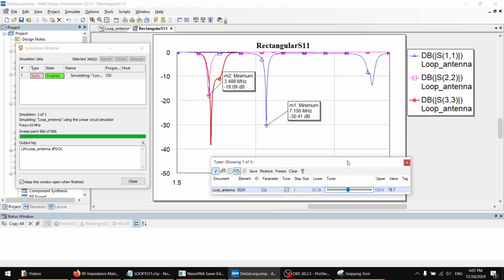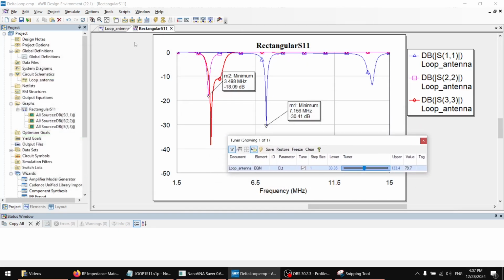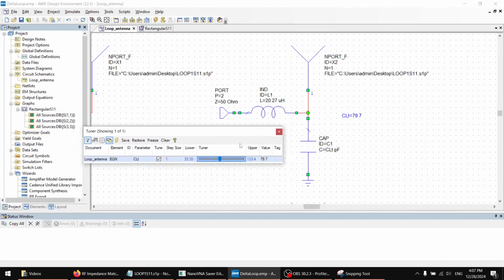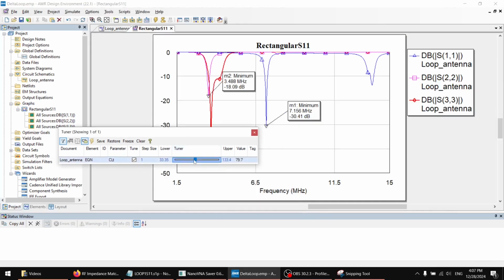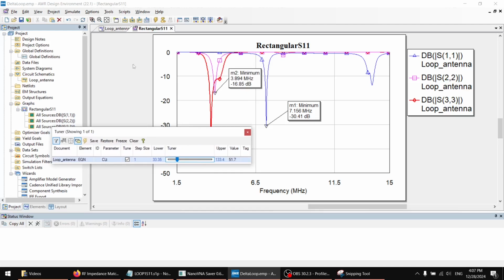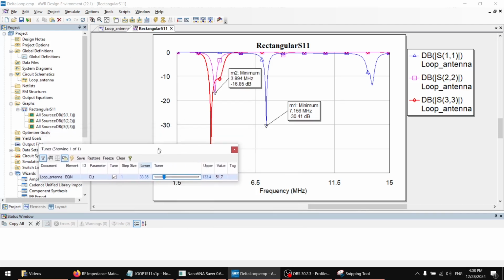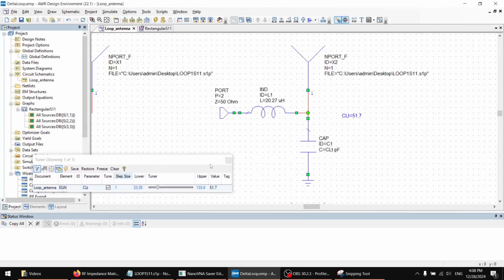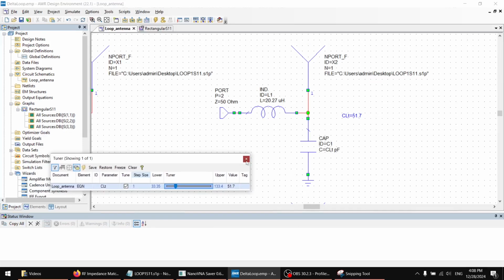So if you design, for example, an automatic antenna tuner or just a tuning circuit for your network that has a switchable, for example, capacitor or variable capacitor, you can very quickly verify whether the capacitor and inductor combination that you used will span the entire band, for example, and you can measure these points, and then knowing those values, you can put them, for example, into a lookup table of your automatic tuner, and you will have a matched antenna, at least in theory, but it's a good starting point.